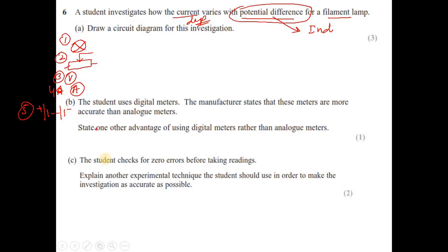The easiest way of understanding a circuit diagram, in this special circuit, is to ignore your voltmeter initially and the rheostat, and the rest of the components, like 3 components, bulb, ammeter, and the battery, you are going to connect in series or a closed loop.